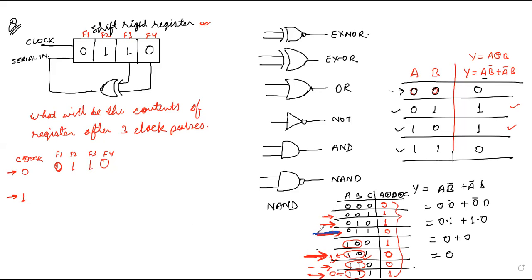इन दिस केस ब्लू कलर, यहाँ पर क्या देख रहे हो? यहाँ पर दो इनपुट्स हाई है, मतलब इवन नंबर ऑफ इनपुट हाई है, तो इसमें आउटपुट 0 हो गया। तो जब भी इवन, यहाँ पर 3 वेरिएबल के अलावा 5 वेरिएबल हो, 10 वेरिएबल हो, 20 वेरिएबल भी हो, अगर इवन नंबर ऑफ इनपुट्स हाई होगा तो आउटपुट विल बी 0। ओके, एंड ऑन द अदर हैंड व्हेन ऑड नंबर ऑफ इनपुट्स आर हाई द आउटपुट विल बी हाई। ओके, सो इसीलिए एक्सऑर गेट को हम लोग ऑड गेट भी बोलते हैं।